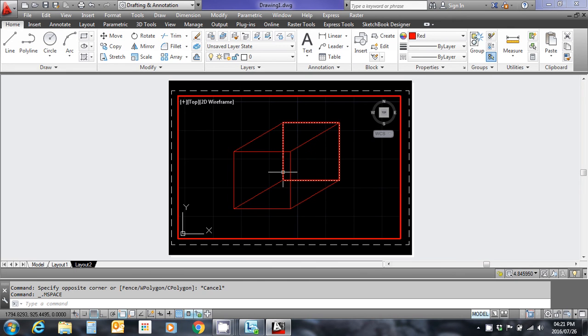I want to now go ahead and set some kind of scale on this. I'm going to try and set a scale of 1 in 1000. Remember, my model space is in meters, my paper space is in millimeters, so 1 meter in model space represents 1 unit in paper space. And if the unit is 1 meter and it's 1 millimeter here in paper space, then I have 1000 millimeters in model space and 1 millimeter in paper space. And if I divide the model dimension of 1000 millimeters by my paper dimension of 1 millimeter, I get a scale denominator of 1000. So that's going to be what I'm looking for.